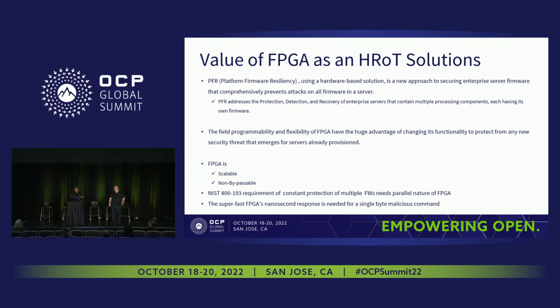And definitely on protection, we talked about recovery and detection. You also need a mechanism for when somebody wants to snoop your buses or send an illegal command, whether it's I2C or SPI commands. You want to understand whether the command is legal or illegal, whether it is an authenticated command or not. Today all firmware updates are done through the BMC, so you want to understand that any update that has happened is authenticated. That's how the protection mechanism works today.